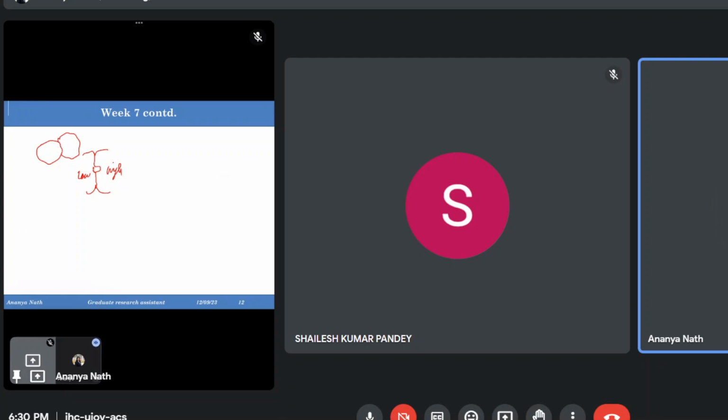But at the same time, the lattice mismatch, or orientation mismatch, between the lattices of these two grains should not be that high in that case. So say there are two grains, and the orientations of these two grains differ by a large angle. The orientation of the lattices has a mismatch between them, and the angle between these two oriented lattices is more. This is why they are high energy, high angle boundaries.